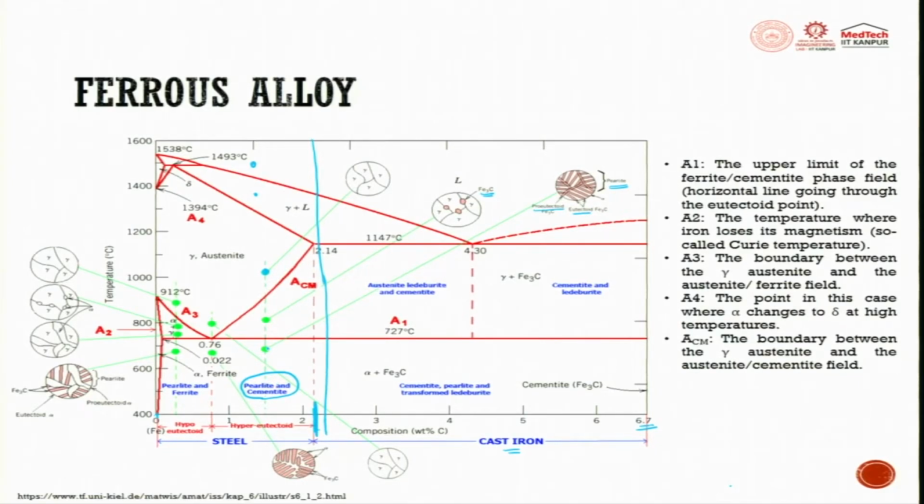Anything below 600, 700 degrees Celsius, or somewhere close to 700 degrees Celsius, whatever you get is frozen up to room temperature. Now, you try to quench it and get it, or from above you try to quench it, and you get the desired microstructure in the workpiece.